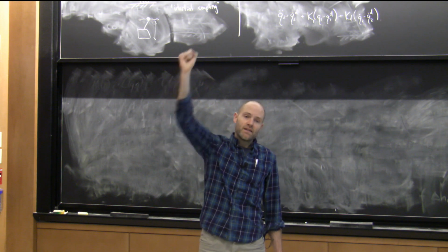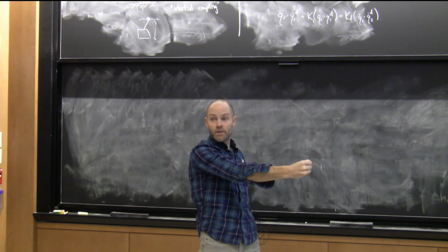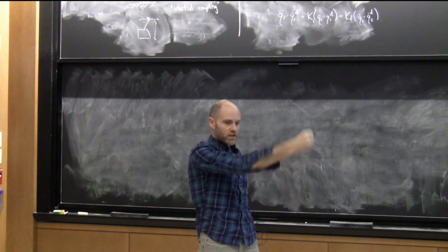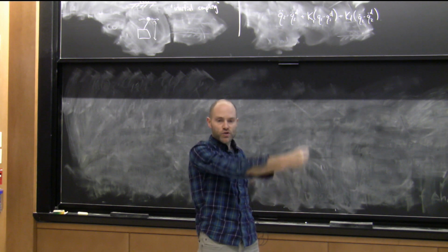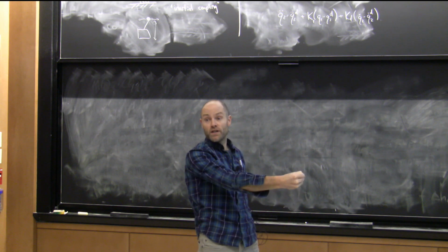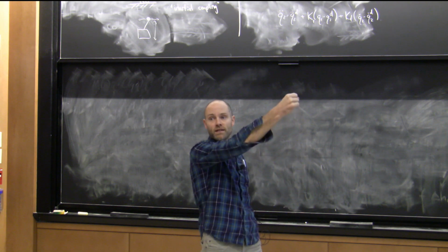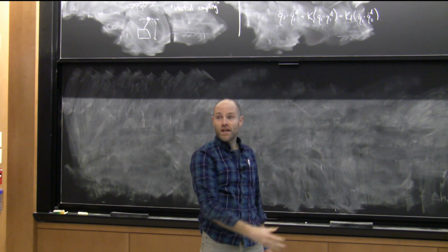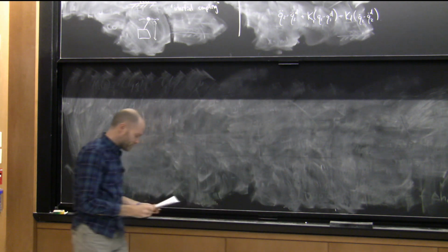But in fact, that one has this problem that it blows up here, and even if you're close to here, any attempt to strictly linearize theta double dot has to go through that transformation, which gets very numerically bad, and then blows up. So that turns out to not be the simplest recipe.